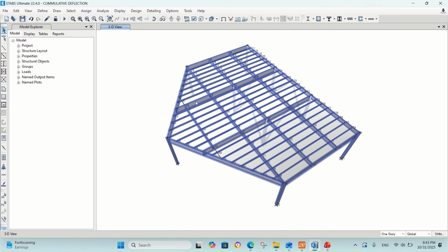at these column grids, and on the sides they are supported on these long span girders as well. And these beams, which are supporting the main beams here, in their turn are supported above these huge 28-meter girders. So the load path is not direct. It's not always joists to girders to column. We have lots of transfer beams due to architectural constraints.